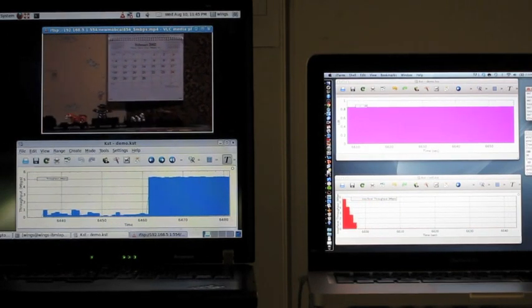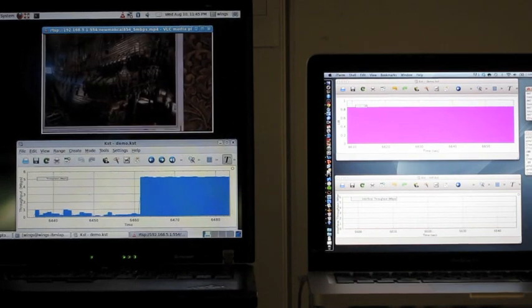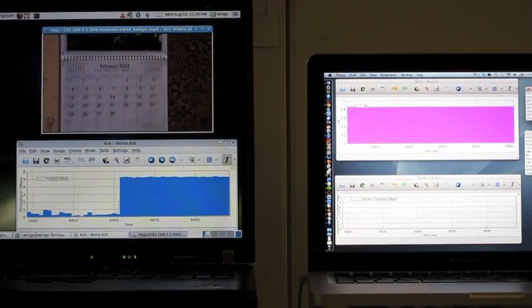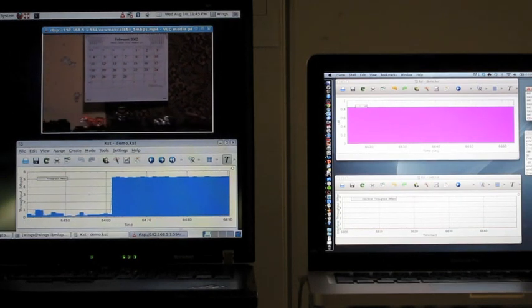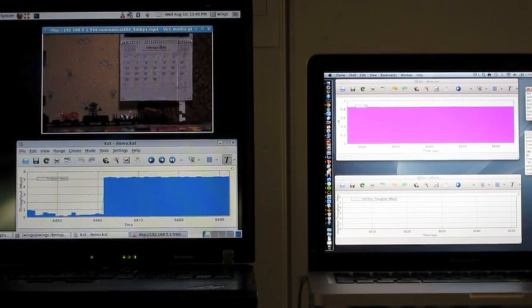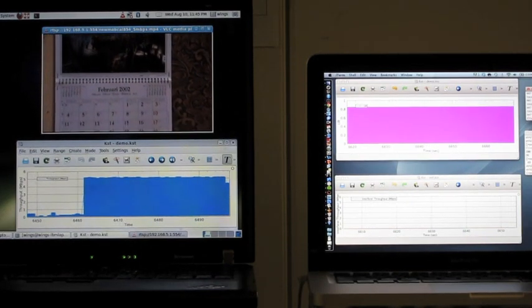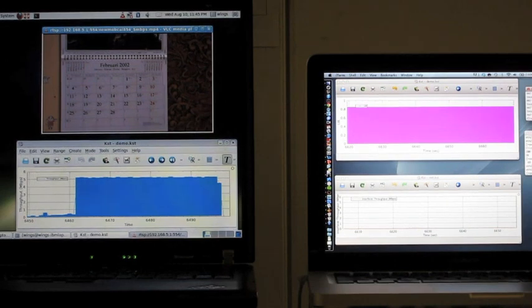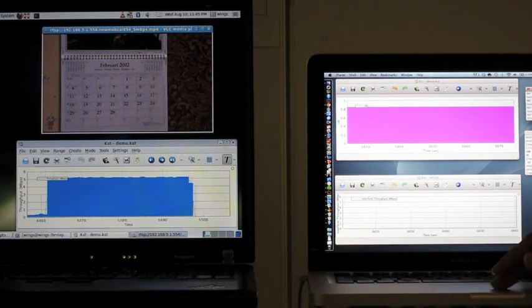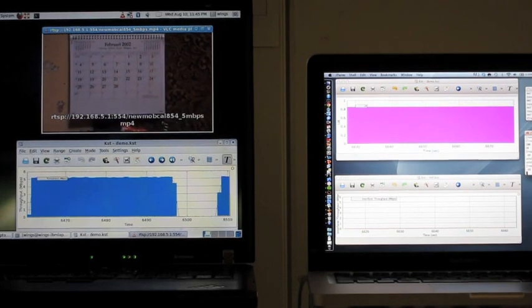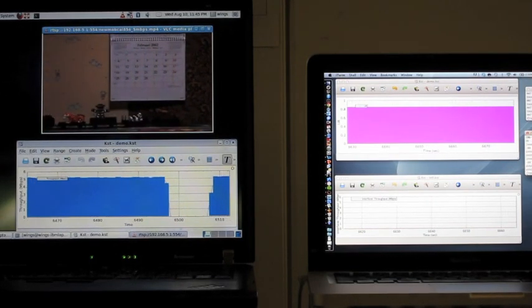So in this particular example, as you can see, our system was able to say that there was an interferer which caused a high amount of interference, which is around 0.8 as reflected in the plot on the top right hand side. Now that I know that this interferer is causing trouble, I can change the power level of this particular interferer so as to reduce the amount of interference. So now I'm going to change the power level of the interferer, and I'm going to restart the interferer again.